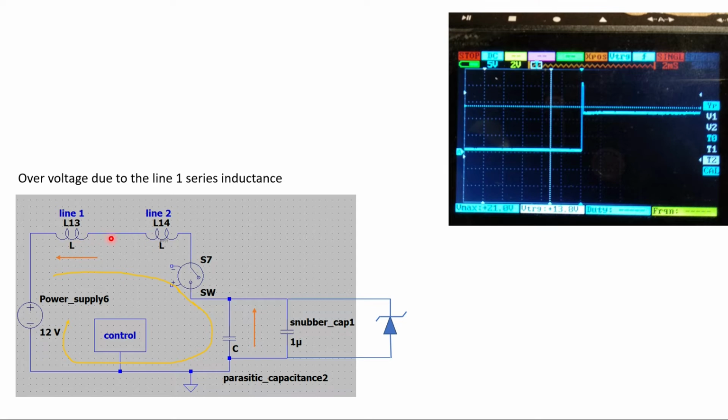the charged inductance is discharged across the capacitance, and this current flows through the capacitor during the transitory. Bigger capacitance means bigger current flowing here. If the current flows here, it also flows through the load, which is the energy that we want to send. Our purpose is to send the maximum energy to the load, so maximizing the capacitors means maximizing also the current here.